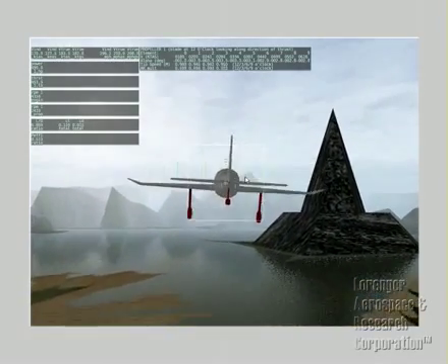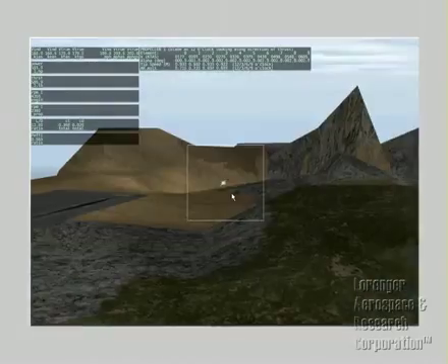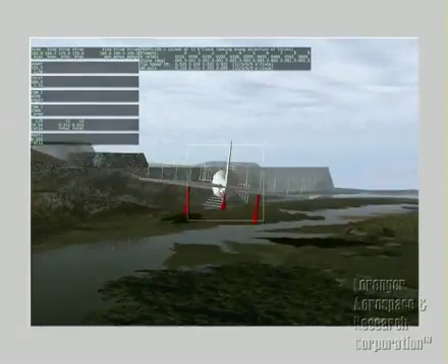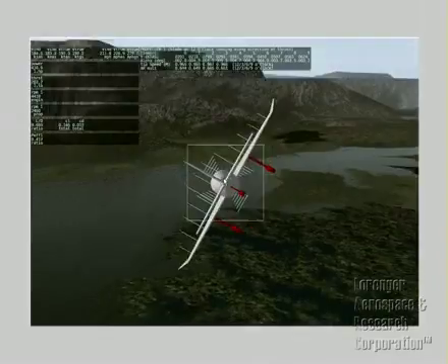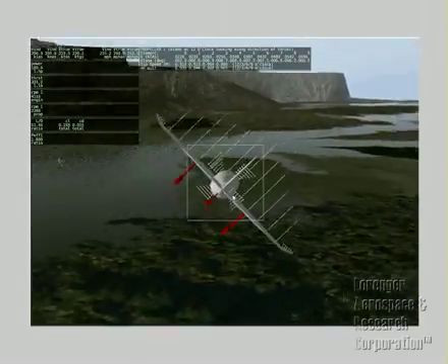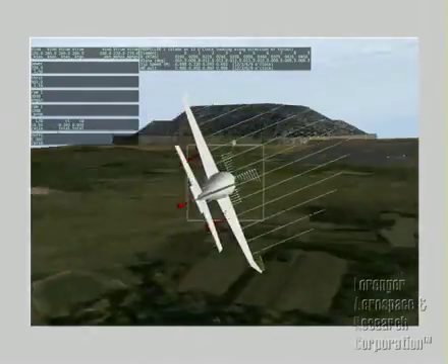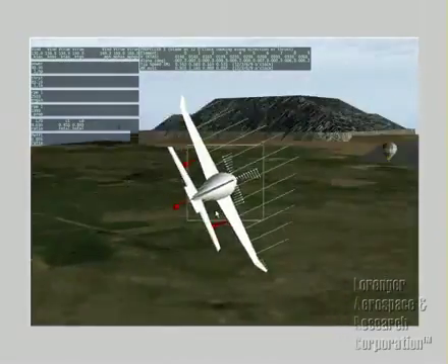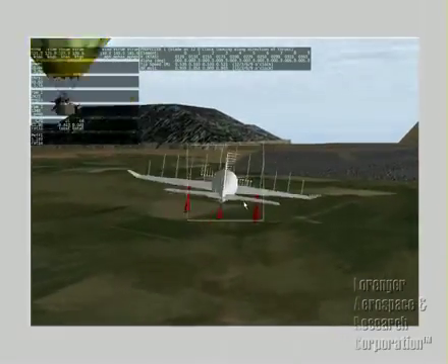At any rate, enough hooting and hollering. We're going to quickly test it, and we realize she's slow. That means the prop efficiency is terrible, 58, 55%. So we're going to quickly do some rolls, stability issues. She's a little snappy, meaning the control deflections are too big. We're going to change that later. We're going to land safely.